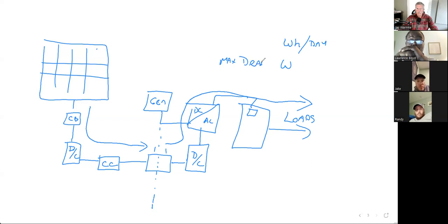in watts. If I turned on everything that could be turned on all at the same time, that's my maximum power draw. And if I don't have an inverter big enough to handle all of that load that comes at it in just 1 second, that inverter is going to screech and shut down. It's going to blow a fuse or a breaker. So I size my inverter in a standalone system based on the maximum power draw that the system could experience in any 1 second. Does that make sense?